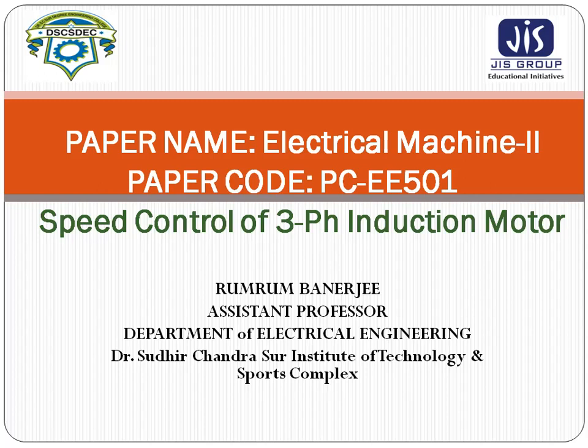The pole changing method, the variable voltage variable frequency method and the stator voltage control method can all be applied to both squirrel cage type and slip ring type induction motors. But the rotor resistance control method is only applicable for slip ring type motor. In squirrel cage type induction motor, the rotor resistance control method cannot be adopted because there is no provision to add external resistance, which is the main advantage of the slip ring induction motor.